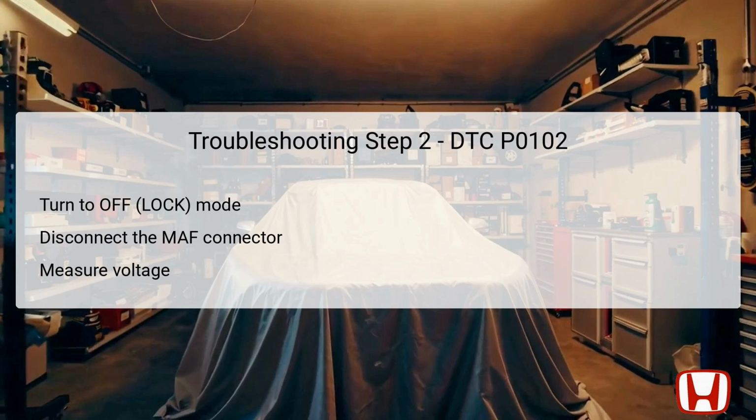If the measured voltage indicates the presence of battery voltage at this juncture, it confirms that the IG1 ACG/IG1 AFM wire is functioning correctly. In that case, proceed to the next step. However, if there is no voltage, this will indicate an open circuit within the wiring, necessitating repairs in the IG1 ACG IG1 AFM wire running between the MAF connector and the number C30 fuse.